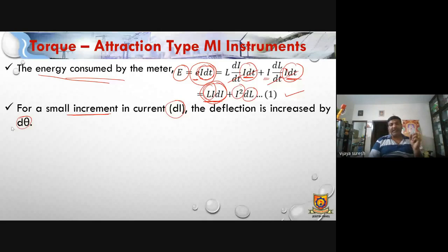Let it be, initially we are measuring at 10 volts. So the pointer will make a display at 10 volts on the scale. Now I am increasing to 15. Then the amount of current flowing through the coil will get increased, hence the angle of deflection also will get increased, so theta will increase. Now the pointer will deflect by a certain angle to get 15 volts on the scale, right? Similarly here, the current increases, so d theta also will get increased.